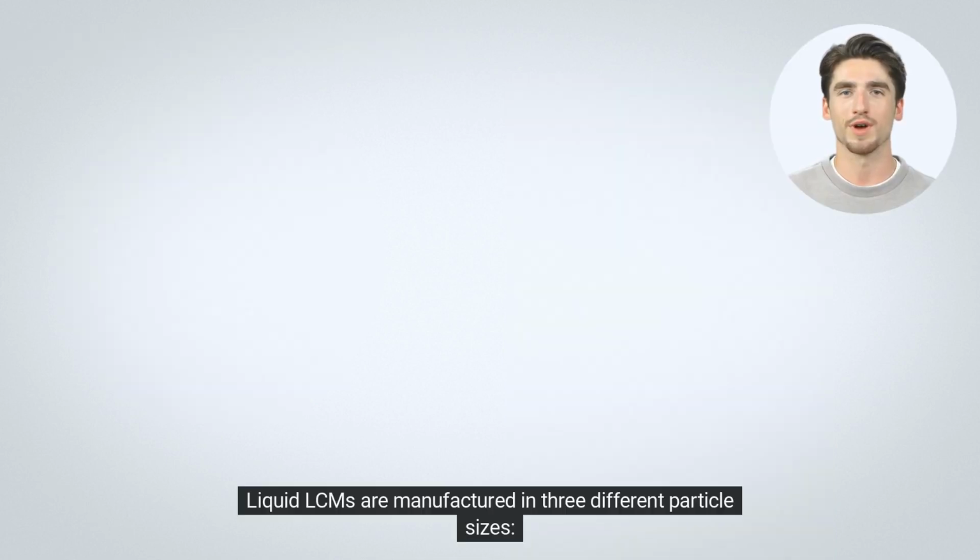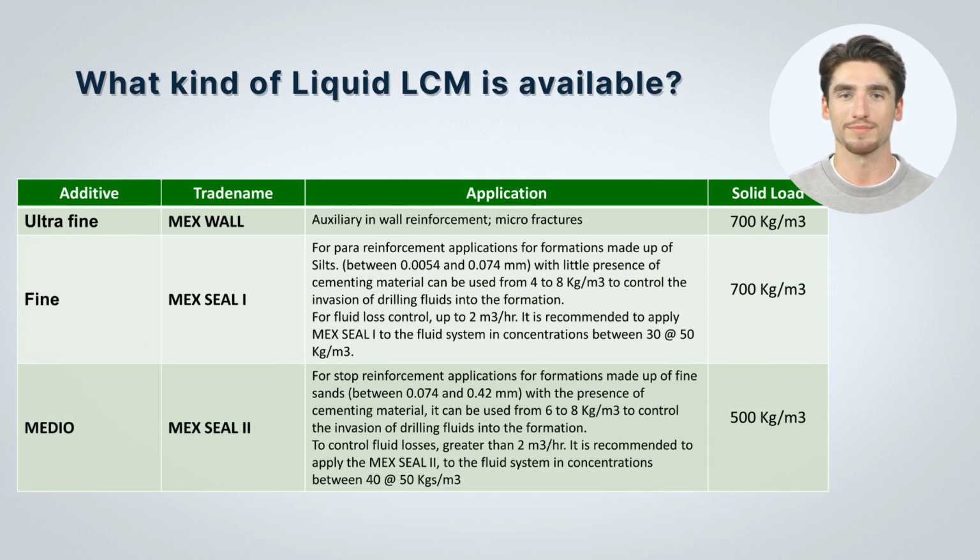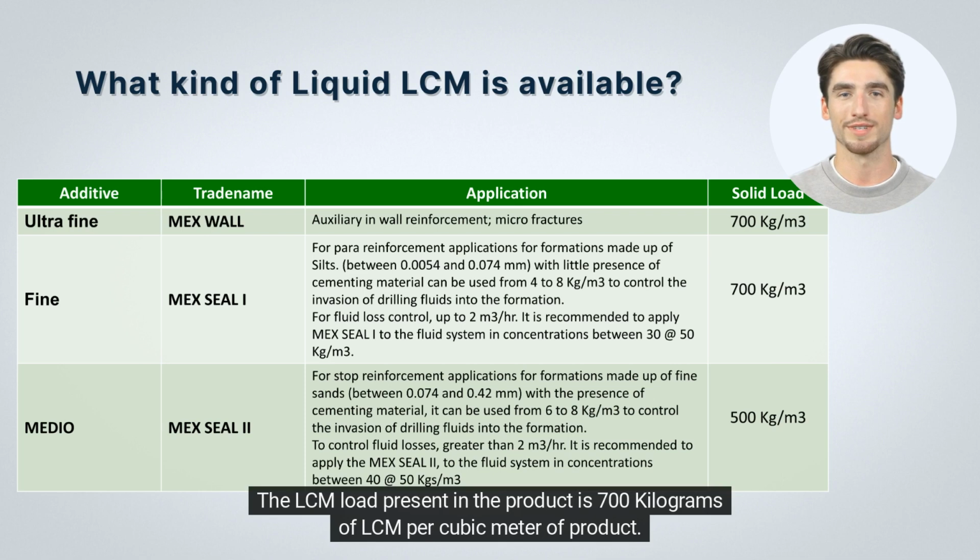Liquid LCM is manufactured in 3 different particle sizes. Ultrafine. It is recommended for stabilization of areas of weak sand that hinder the progress of drilling. The LCM load present in the product is 700 kilograms of LCM per cubic meter of product.